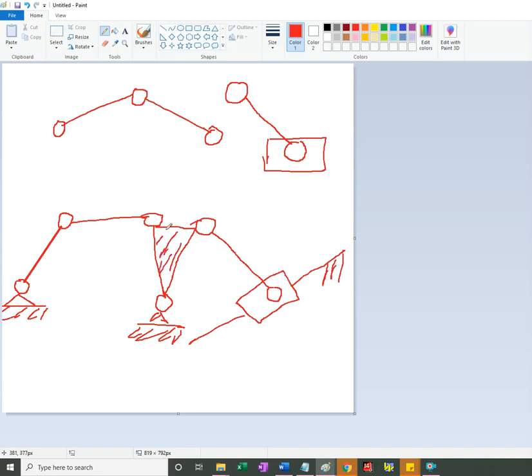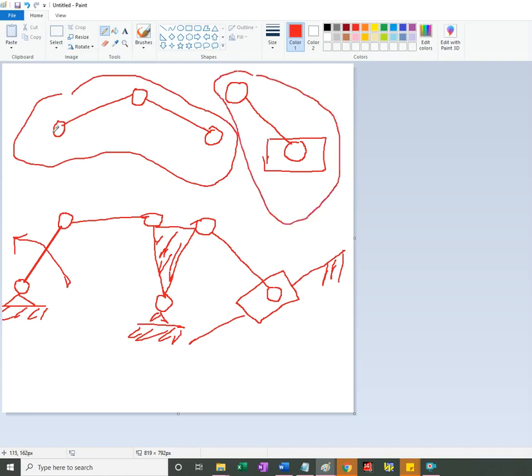Again, this is a ternary link, a solid link. As separate units, these have 0 degrees of freedom. We call this a potential joint; there will be a potential joint at the slider, and this one is a potential joint. Having 0 degrees of freedom by themselves, you add them to the original 1 degree of freedom crank, the simple mechanism. You made the 4-bar. You came in and further amplified it to a Watt 2 linkage, with a translation prismatic joint.